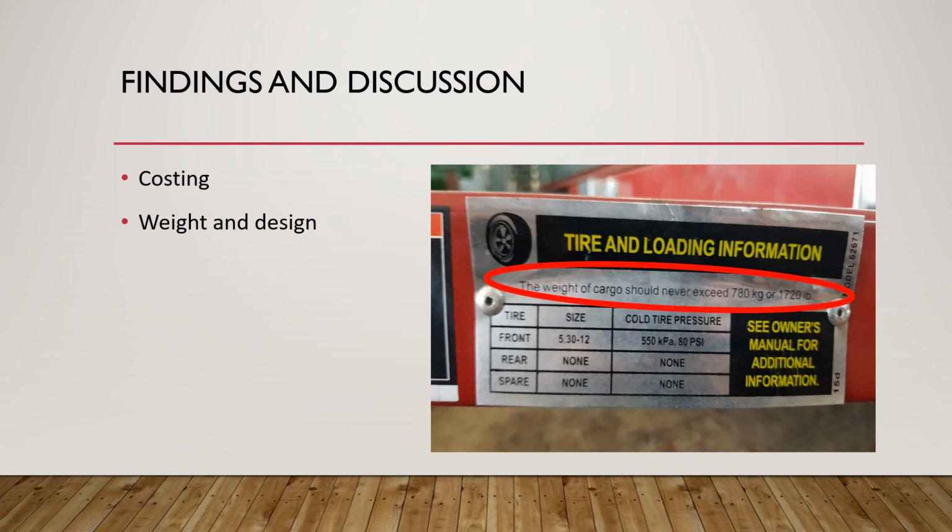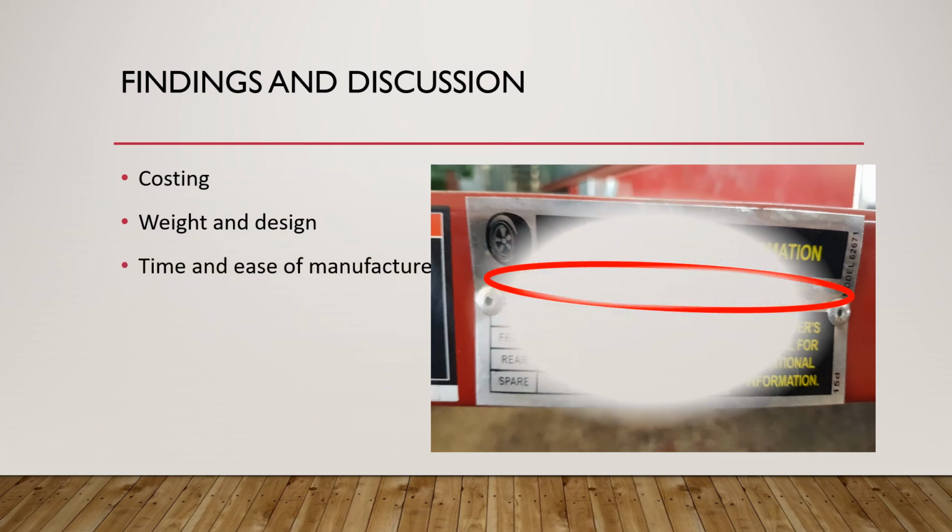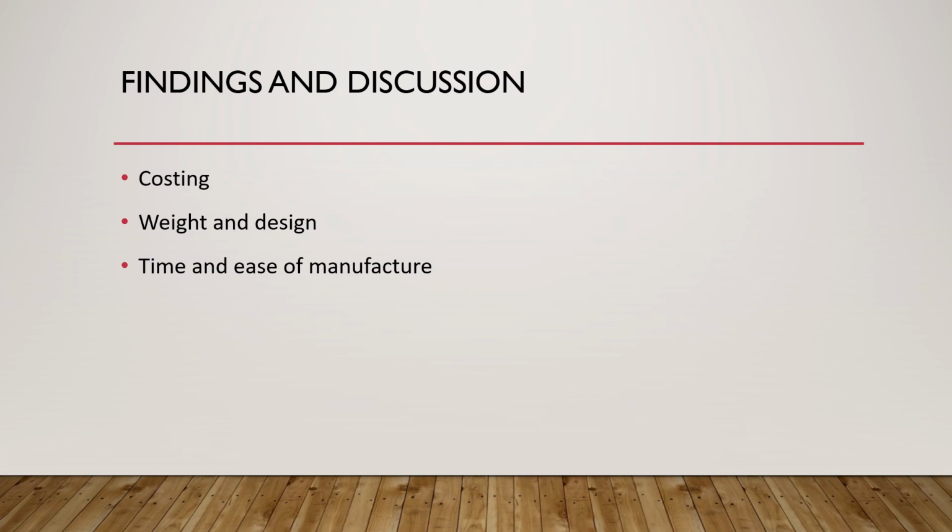Additionally, the tests conducted showed that the internal framing was a bit over-designed, with a factor of safety of 11. Therefore, materials can be reduced. The internal counters took 4 days to build. This is from the cutting of materials to having it welded and ready to be covered. This can easily be reduced to 2 days by commercializing the process. This also illustrates that the cart can be easily manufactured.